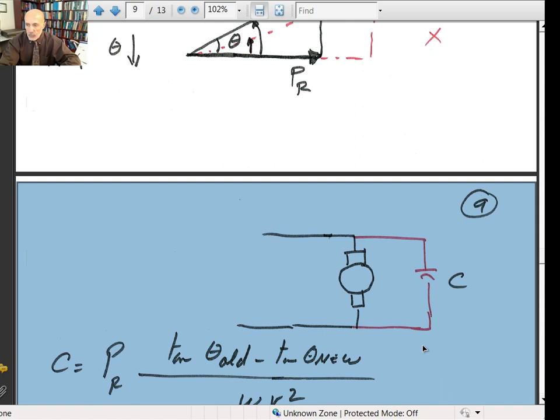Sometimes the same one will kick in with a different value, but the 3-phase motors don't need starting capacitance because they always have a phase shift, and that's the advantage of a 3-phase motor. Not only is there no need for a starting capacitance, it also has less vibration than a single phase.